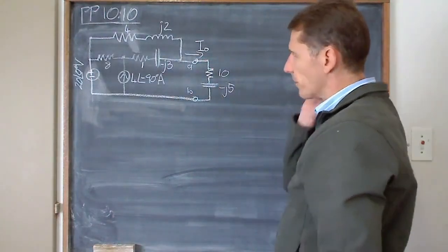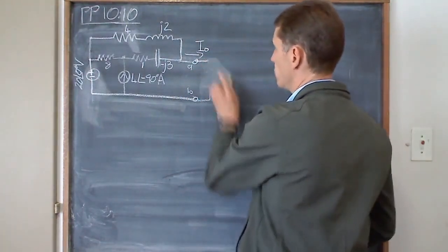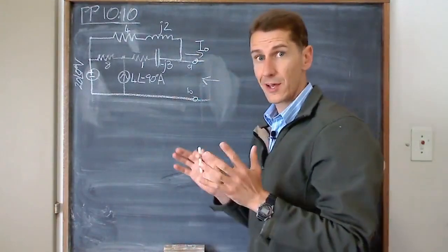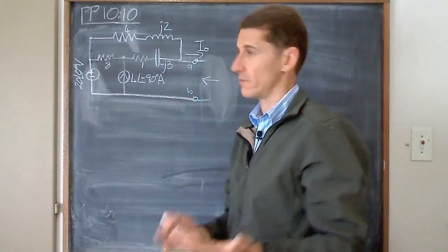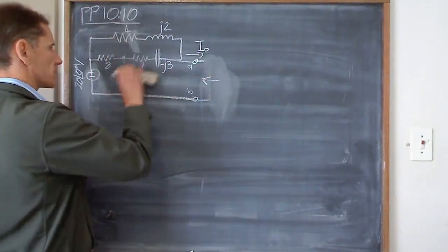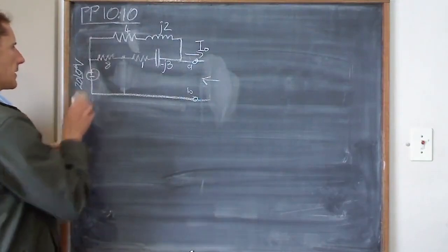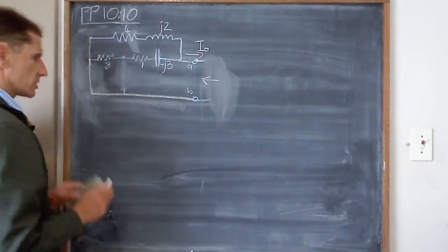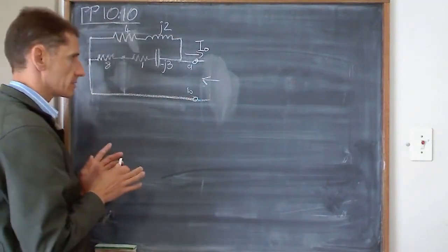All right, first let's find the Norton equivalent. What is that going to look like? For the sake of space, I'm just going to remove this for now, and we're going to look into these 2 terminals, but it's the Norton equivalent impedance, which is exactly the same as the Thevenin equivalent impedance. So let's zero our sources quickly. The current source disappears. I must just remember to put it back now. Now I wrote on wet board, now it doesn't want to go away. And the voltage source is going to be, I made problems for myself, a short circuit. So this is what the circuit looks like for my equivalent impedance.